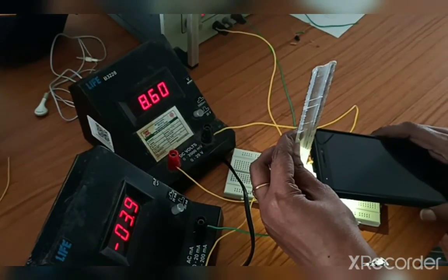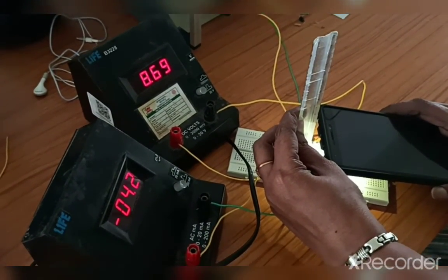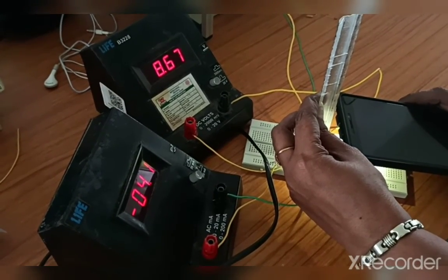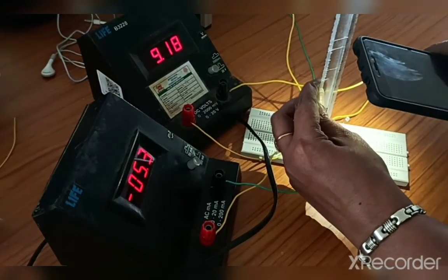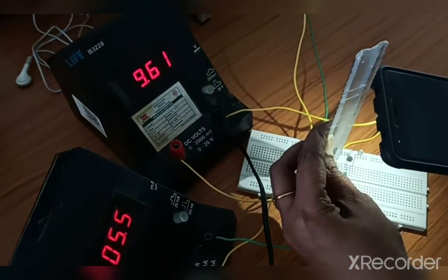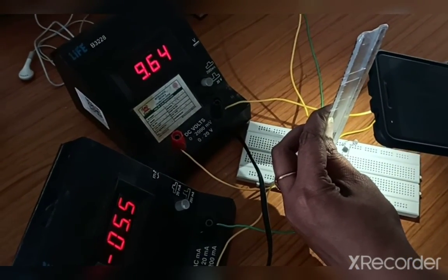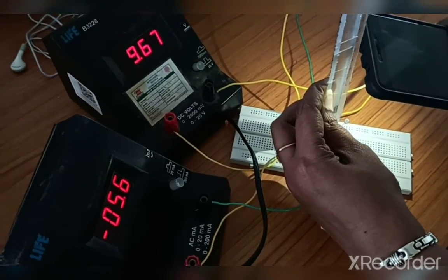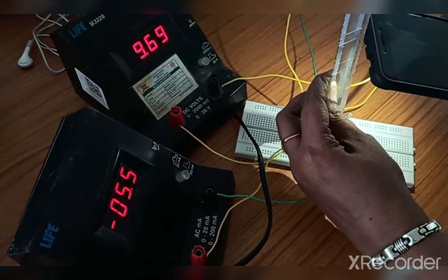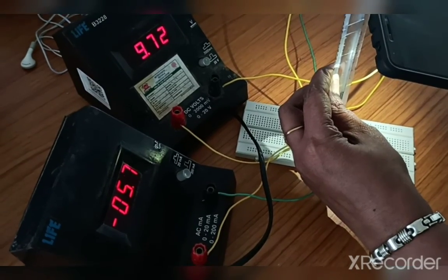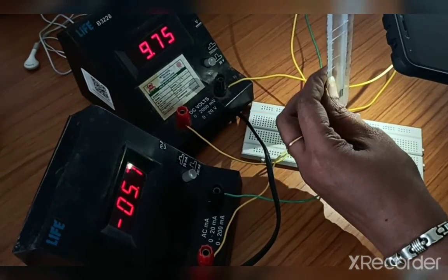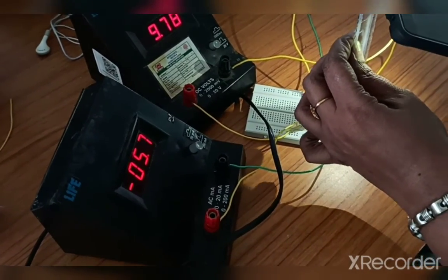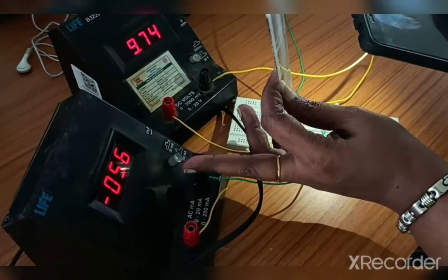Negative clamper means the new negative DC value is going to be here, minus 5. So here I am going to clamp this sinusoidal waveform to a new DC level, and that is called a clamper. If I construct a negative clamper, my waveform will go downwards. If it is positive, my waveform will be shifted upwards. By the direction of the diode itself we can say which direction the waveform is going to be clamped. So this is a negative clamper.